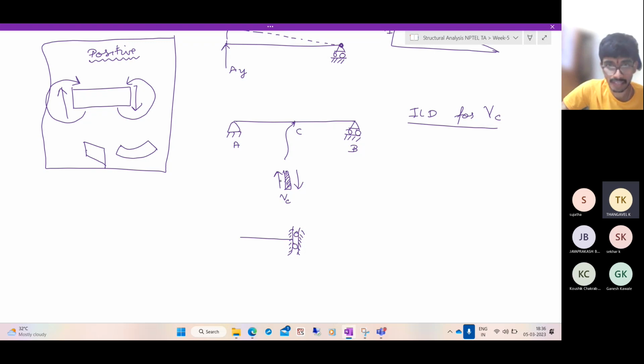But if on the left it is like this, what will come onto the beam? The opposite will come because internal forces have to cancel each other. So at the point A is the point B. So opposite to this should be applied on this span, opposite to this should be applied on this span. So how does it deform? This cannot move, right? Here we cannot have any motion because it is a support. So the deflected shape will be something like this.